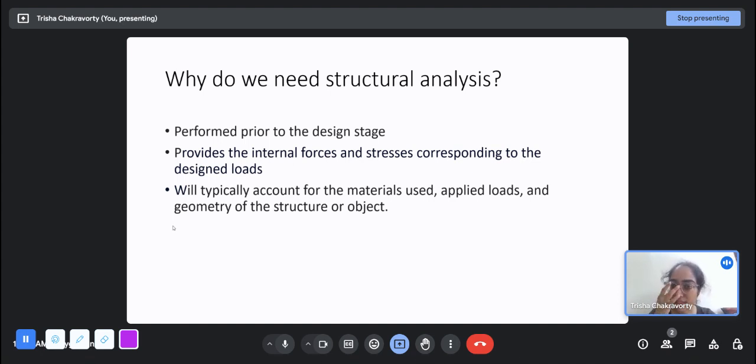So structural analysis is the process where we are given a structure, the boundary conditions and the overall loading on the structure, and we find out the loads and displacements of each member of the structure, because then we are going to design each member at a member level. We cannot design a structure overall. So we will see what demand I'm expecting on a beam or on a pier or anything, and then we determine the geometry and the material. So that is design: first structure analysis comes, then design comes.